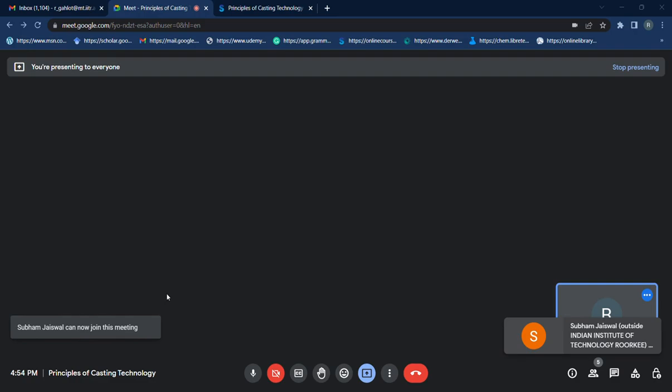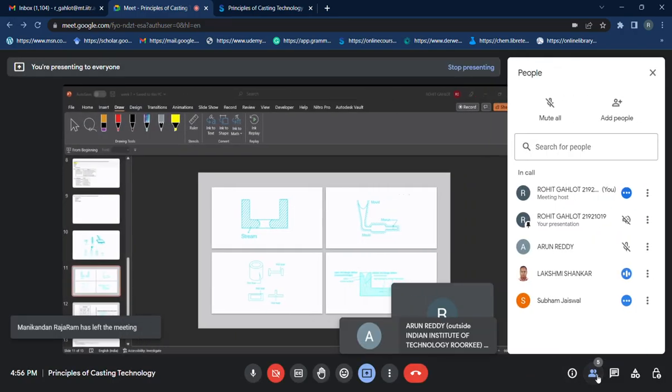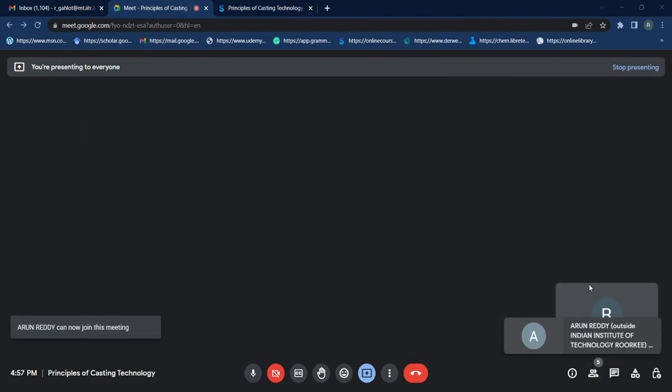So a tearing effect will come due to the different cooling rates of the parent metal and the electrode material. I think because they have different melting points and also different cooling rates, due to this this hot tear will occur. Yeah, it may occur.